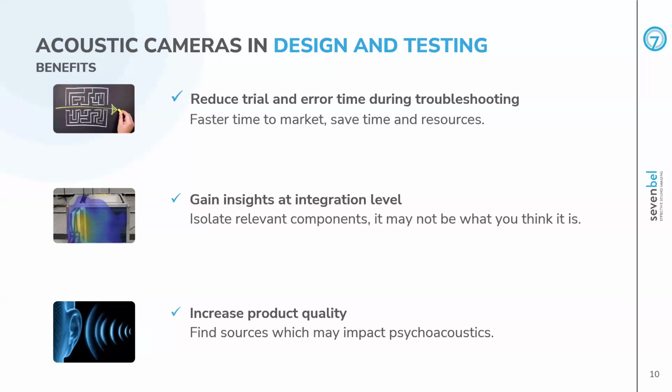So how can this help you in designing or testing HVAC products? Well, it will reduce the time for trial and error in comparison to traditional microphonic solutions where we place a lot of microphones and try to understand based on level differences. This is a much more immediate solution. It will immediately show us where a sound source is and what its characteristics are. We can isolate different components in the machine, which is again something we cannot do with microphones alone, or not in a very precise way.